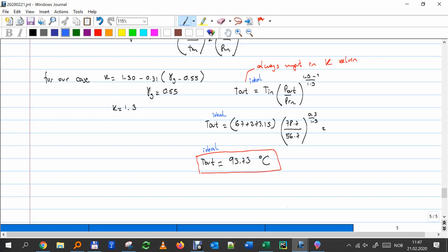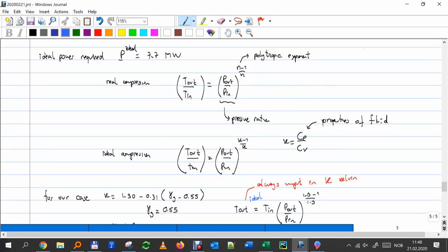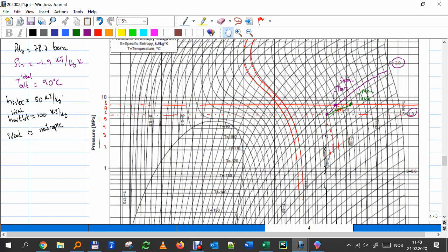The manufacturer usually says the discharge temperature of the compressor has to be below 140 C to avoid problems in the seals of the compressor, avoid structural integrity issues in the pipeline, and avoid vaporization of the hydrate inhibitor. Because of the compressor, you have some seals made of rubber. So if you go too high on the temperature, then you will have some problem. So we know ideally we just get to 93, but now we have to know for the non-ideal case, with this n, how far in the chart we are going to go.